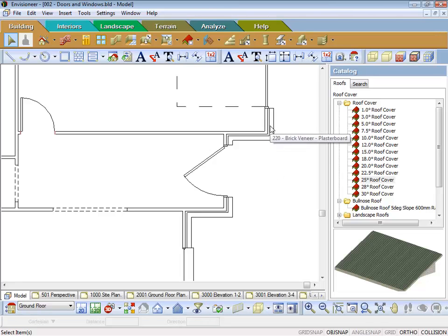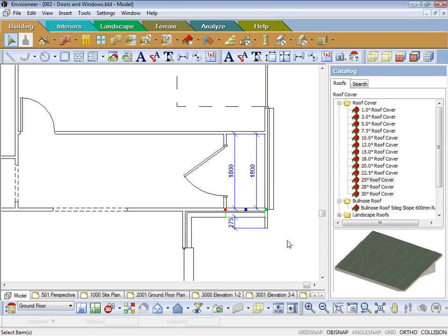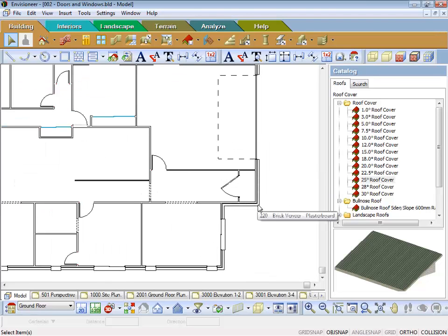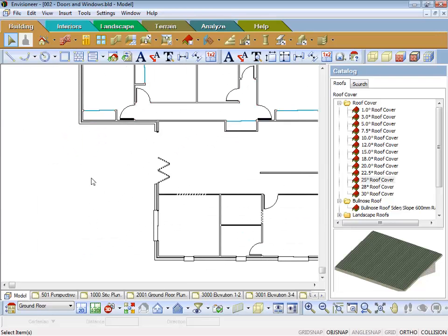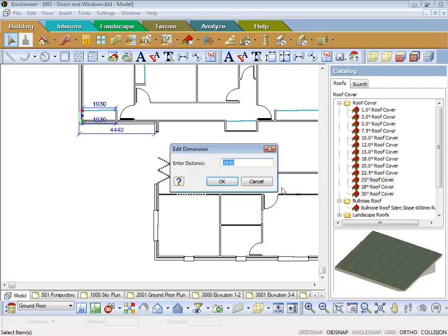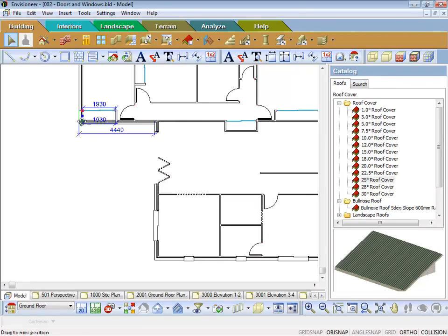Now I'm going to grab this wall here and just drag that out, and grab this wall here and drag that out. What that does is temporarily take away the veneer skin going around the front door area, but it creates the shape to give me the roof. Exactly the same over the back here. I want to bring this wall down, just by grabbing that green point and dragging it down.